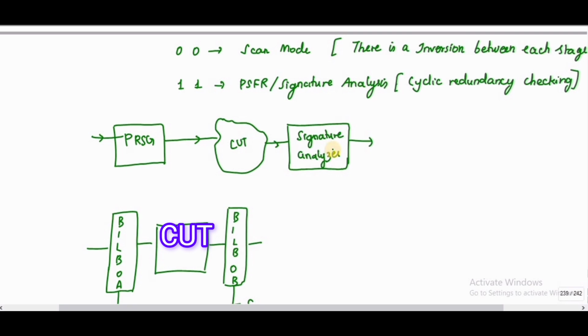So if I want to check the memory BIST, on many chips the memory accounts for the majority of the transistors. So a robust testing methodology must be applied to provide reliable parts. So in typical M-BIST schemes, multiplexers are placed on the address and data and control inputs for the memory to allow direct access during the test. So during the testing, a state machine uses this multiplexer to directly write checkerboard patterns of alternating ones and zeros, and the data is read back, checked, then the reverse pattern is also applied and checked.